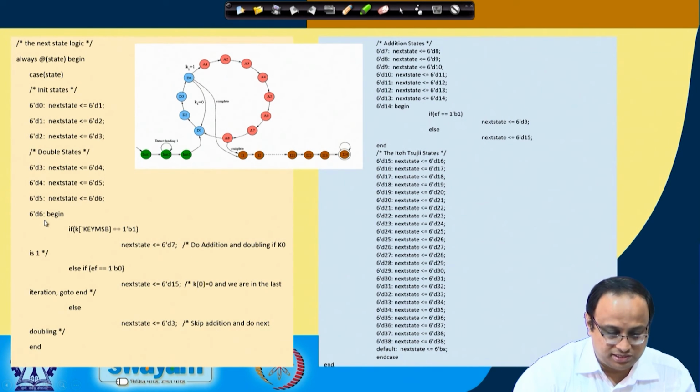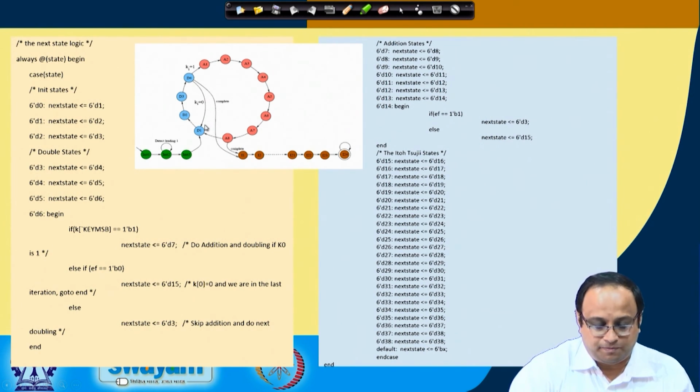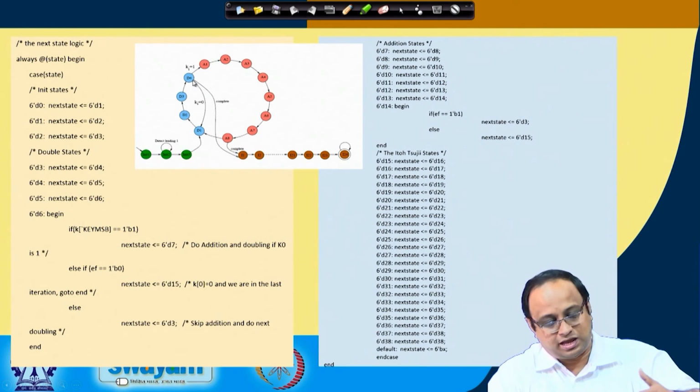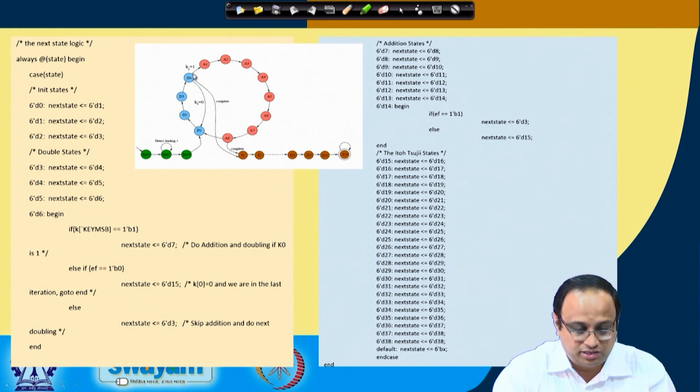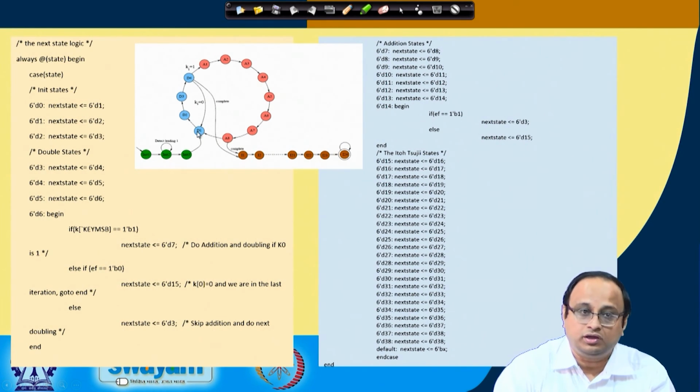Okay. So, that essentially is this part where you have a conditional key statement, and depending upon that, from this clock cycle you either do a doubling, and you follow a doubling with a doubling, or you go into the addition step basically. So, you either go from here to here, or you go from here to here, okay, and that depends upon your key bit. Okay.